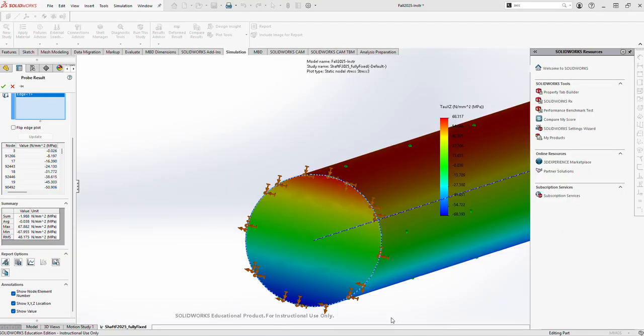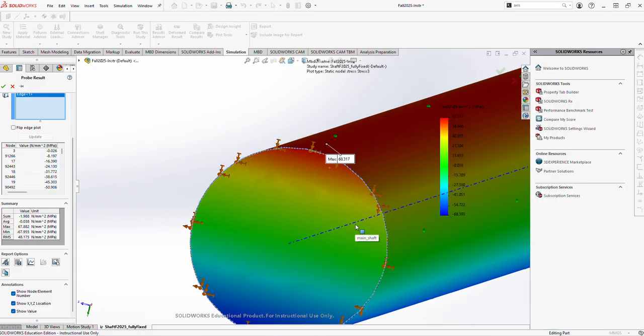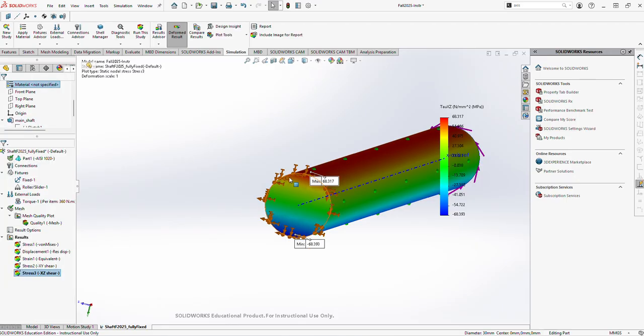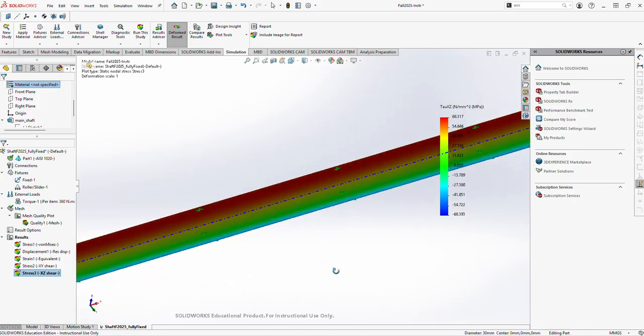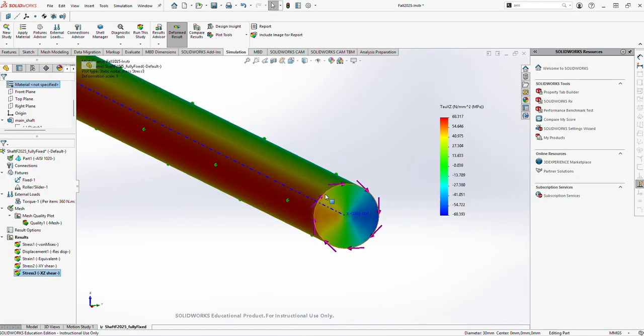This is something that I will be doing very quickly. Let me close this. Now we are going to calculate the angle of twist. But keep this in mind: for angle of twist, we cannot do that on the constrained edge, because the constrained edge will have a zero displacement. That's why the edge is constrained. So we'll have to go to the free edge on which we are actually applying the load, and this is the furthest away. This is where the length is L, and this is where we are going to plot the displacement.